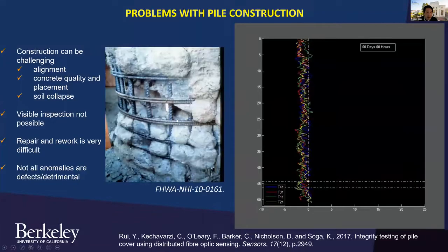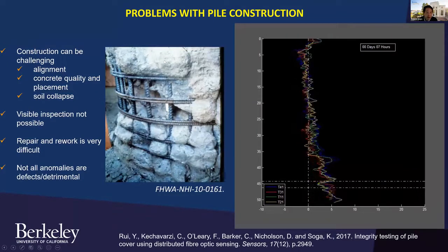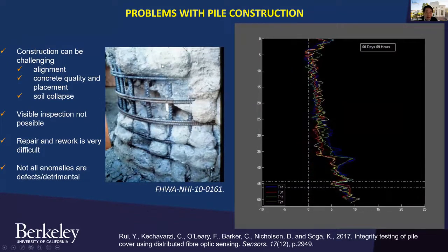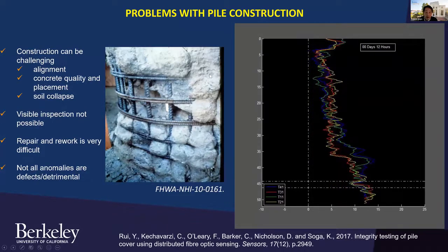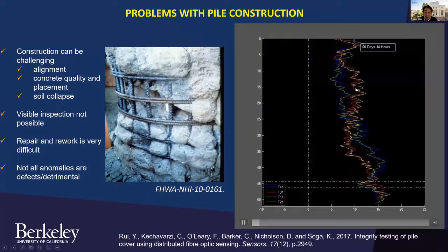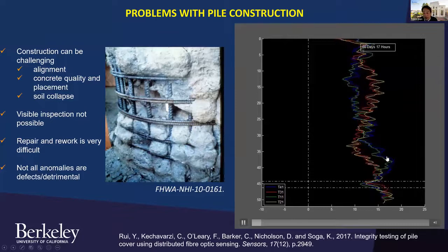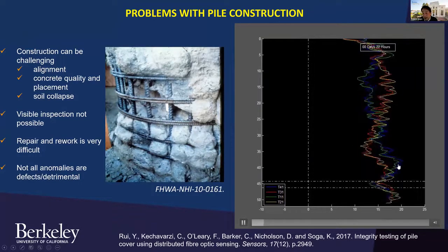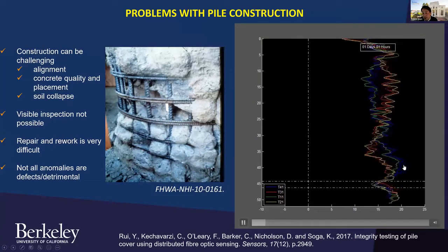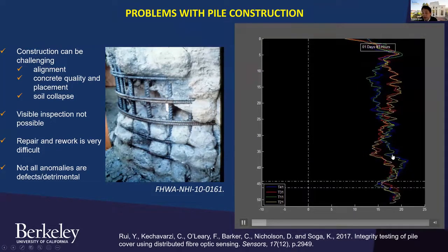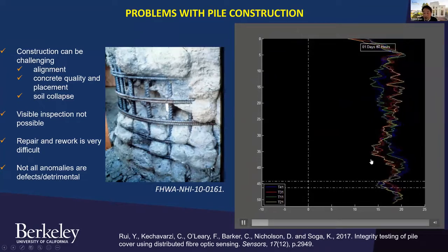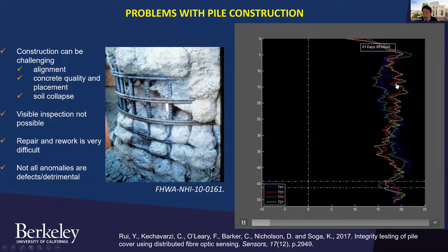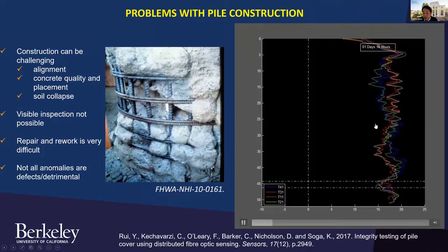At the same time, when you just pour your concrete, the concrete starts to cure, and that will generate a lot of heat, and then the temperature in the concrete will rise. And you can monitor that using fiber optics. So you can see the temperature rise with time. This is 20 hours, one day. And then you can see that the blue and green are heating more than the other side of the pile. And that flips on this particular one. So we have about 1,000 points per line.